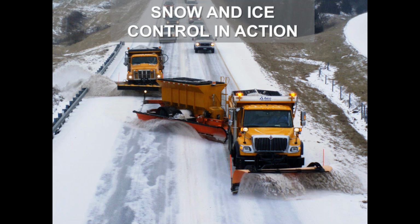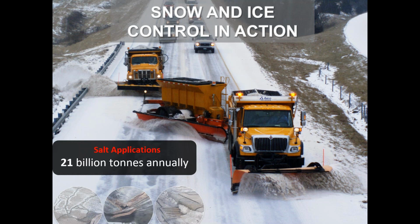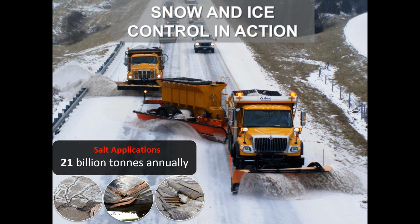So to minimize the safety and mobility impacts caused by these winter weather events, it's critical that we perform snow and ice control. And we apply this systematically by integrating various winter road maintenance operations, including snow plowing, sanding, and salting. Not only can efficient and effective winter road maintenance programs reduce the risk of vehicle collisions, but they can also facilitate better traffic movements. However, transportation agencies typically spend a lot of money, around 3.3 billion annually, for conducting various winter road maintenance operations in North America, and apply about 21 million tons of salt annually, which in return brings a detrimental effect on the existing infrastructures as well as the environment.